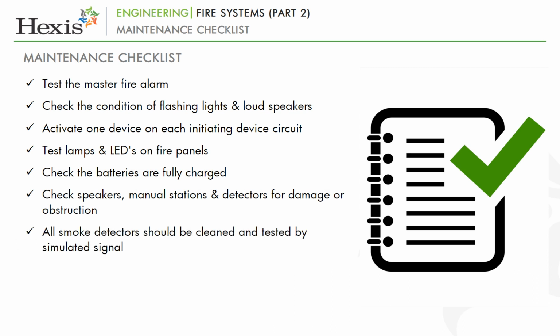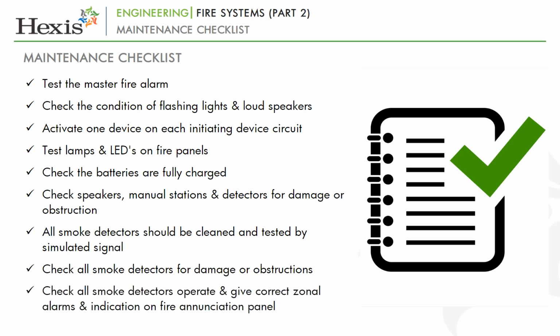All smoke detectors within premises should be cleaned out of dust and tested by simulated signal. Check all smoke detectors for damage or obstructions. Check all smoke detectors operate and give correct zonal alarms and indication on fire annunciation panel.